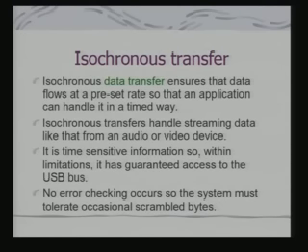If 1 or 2 bytes are scrambled in a video frame which is being displayed, it might not really affect the quality of the picture, or there can be software post processing to take care of this kind of scrambled bytes. This is a very basic principle which we are discussing in the context of USB, but it is true for various other protocols which support isochronous transfers.